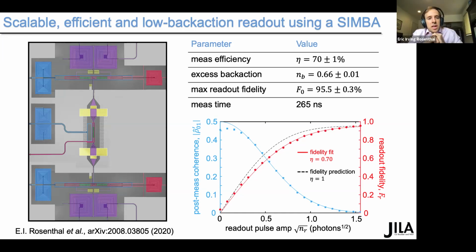So to my knowledge, basically every experiment in our field, aside from the sort of niche experiments like ours that are trying to replace these circulators, has 2 or 3 of these magnetic devices before their HEMT amplifier, which is the amplifier at 4 Kelvin, which is rather noisy. It's also, to my knowledge, every experiment that is trying to scale up and has more than 1 qubit in their fridge only uses these ferrite circulators to date.